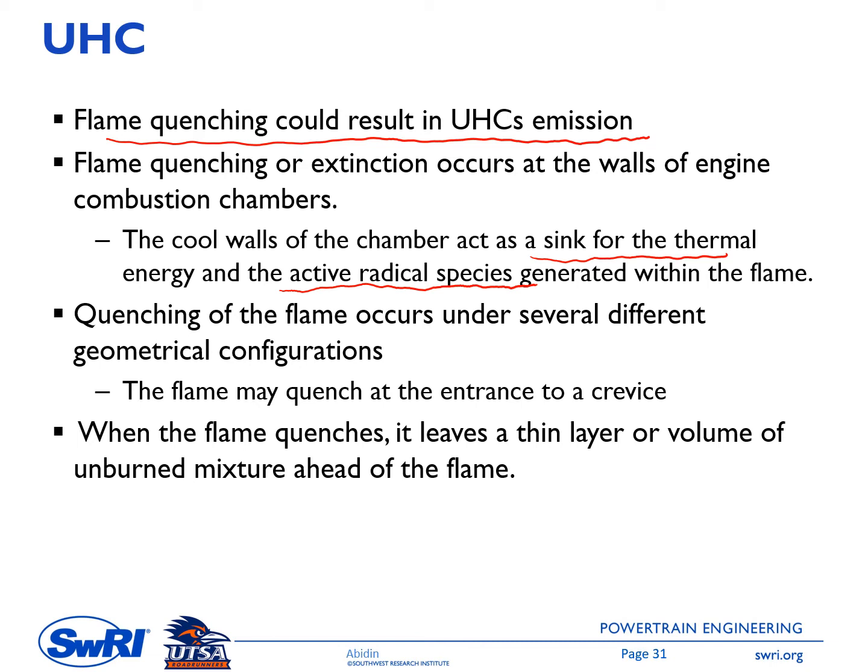One of these flame quenching cases occurs when the mixture or the flame tries to enter the crevice zone. Then there might be flame quenching at the entrance of this crevice zone. When the flame quenches, it leaves a thin layer or volume of unburned mixture ahead of the flame.